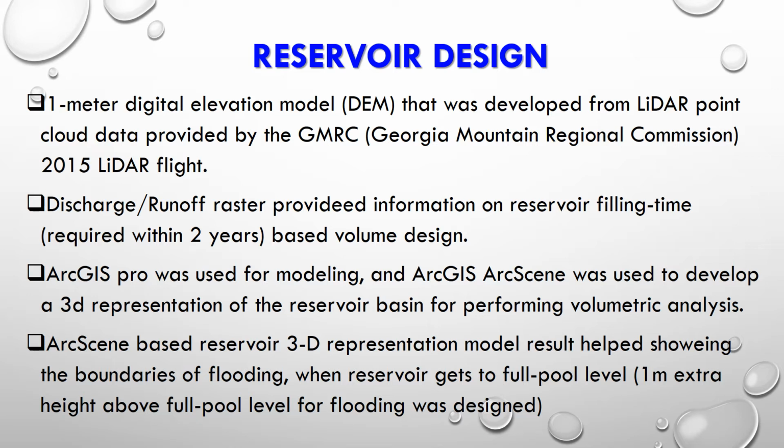Then we used ArcGIS Pro for discharge modeling purposes, and the ArcScene module was used to develop the 3D representation of the reservoir basin for performing volumetric analysis. The ArcScene based reservoir 3D representation model result helped us show the boundaries of the flooding. When the reservoir gets to full pool level, we actually have 1 meter of extra height above the full pool level for flooding or inundation area design.